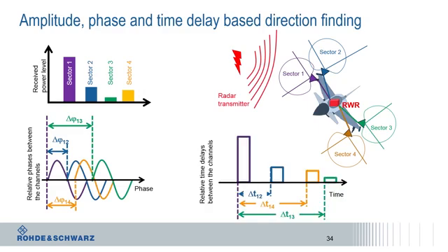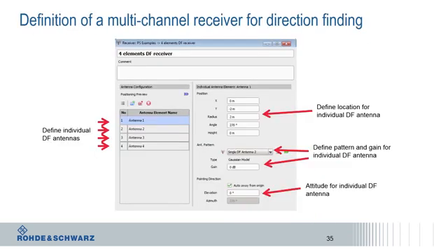If the timing is accurate enough, it can also determine the time of arrival of each radar signal. In addition, use amplitude, phase and timing in order to find out where a radar signal is coming from. So this is giving much more information to the radar warning receiver than only looking at the pure amplitude. For these scenarios, the Rohde & Schwarz pulse sequencer software has the right tools on board to simulate exactly test cases to test the radar warning receivers.